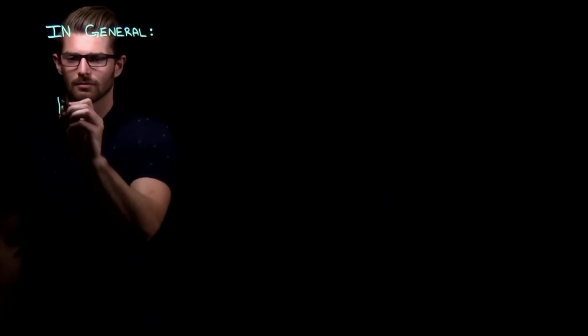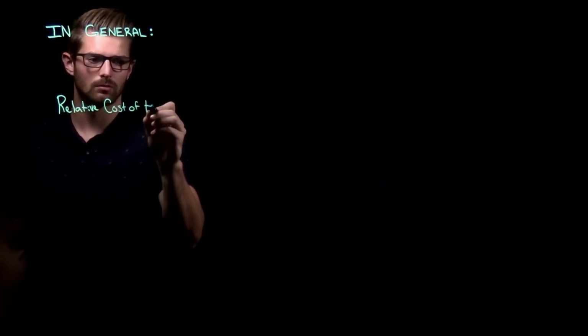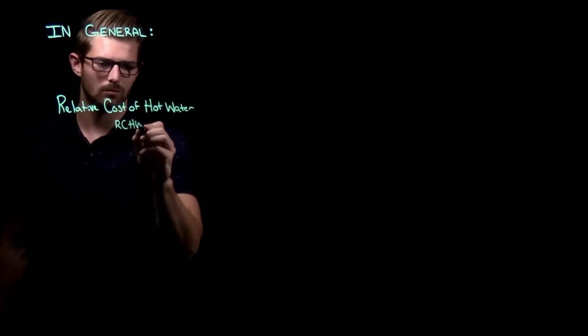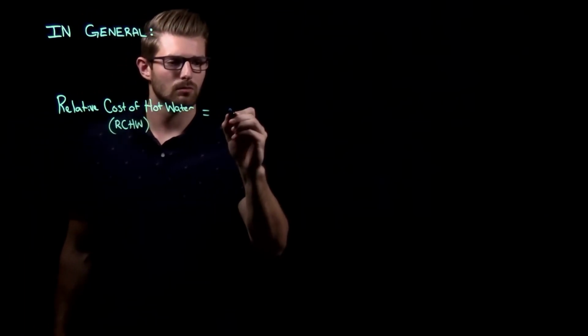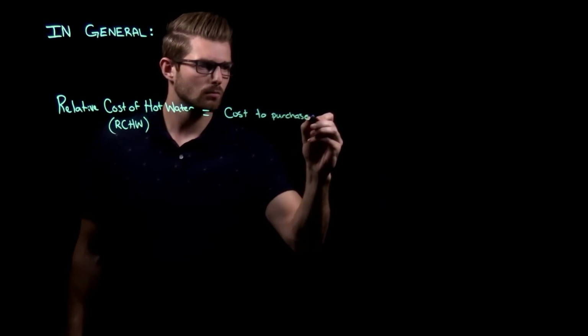Hello again. In this video, I will show you how to properly assess the relative cost of hot water in your facility. The cost added by heating is often overlooked. However, the cost to heat a given volume of water can be 4 to 7 times the cost of purchase. Therefore, calculating the relative cost of hot water can help realize savings that have previously been overlooked.